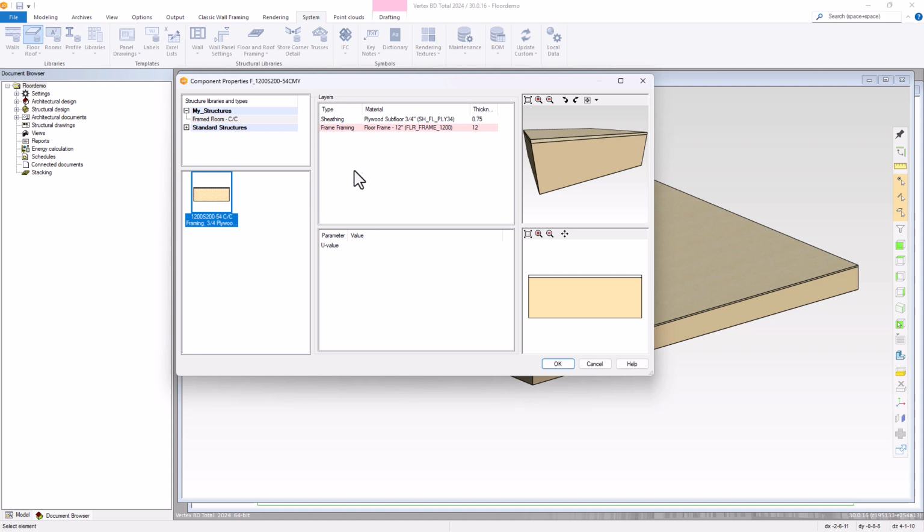The floor consists of two layers, a frame layer and a sheathing layer. Select the top layer material. This is the sheathing plywood material. Right-click to open the Layer Editing menu, which includes tools for inserting layers, above or below a selected layer, deleting selected layers, reorganizing layers, and accessing a framing tool, if applicable. Select Insert Above to add a new layer above the sheathing layer.